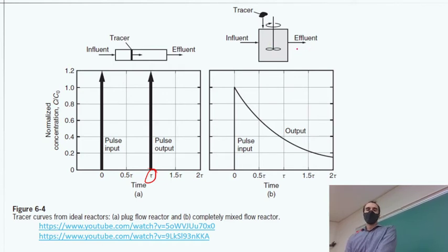We've got C here and C here. And the C naught was just right when we added it, we measured it, that was C naught. So what's coming out, though, is whatever dilution state it is at. And so we just see that tracer amount decrease over time, and it's not like it's all out by that first hydraulic residence time, because there's still water with some stuff in it. It's just slowly leaking out, being diluted out. So it'll take a little while.